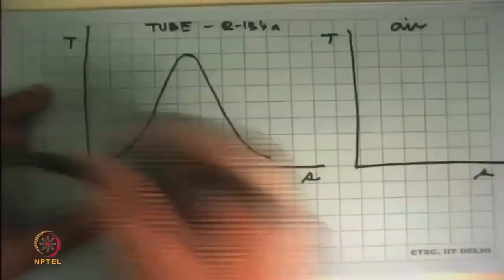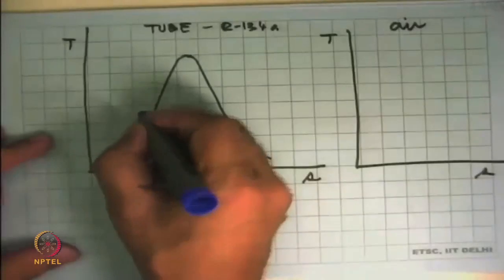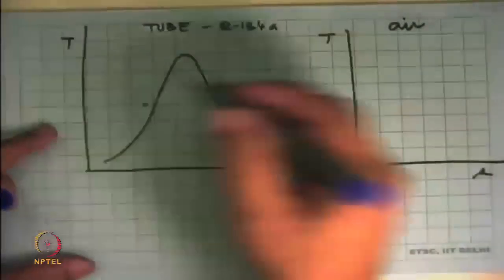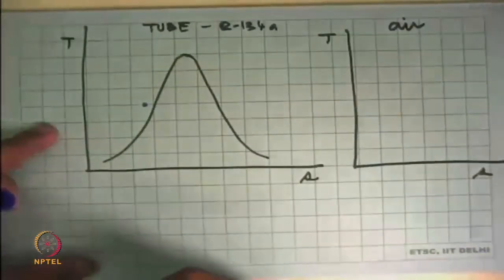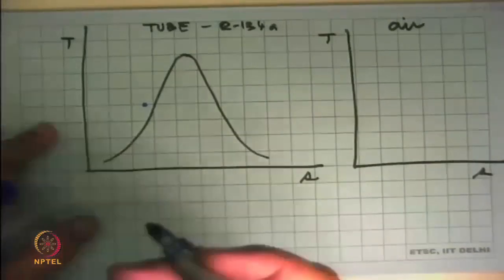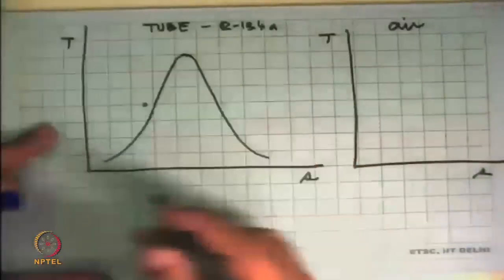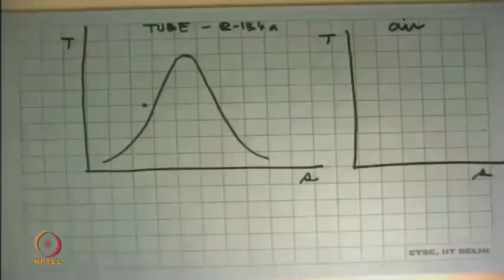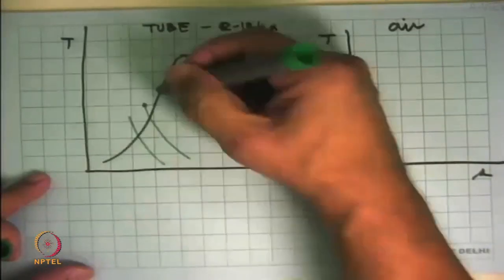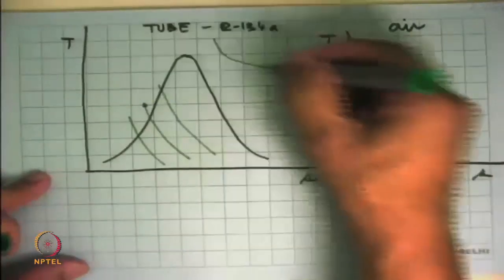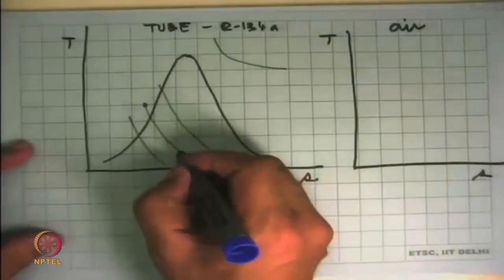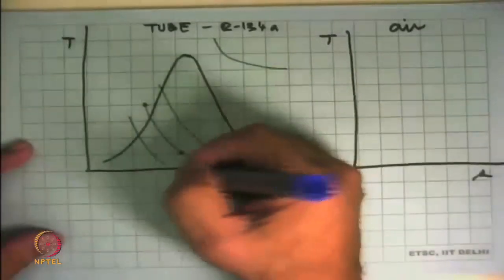So in this case, what is happening is that at the end of the condenser, we got slightly subcooled liquid, and this was throttled. Now, throttling is a highly irreversible process, so we don't know what states happen in between. But at the end, we know that the enthalpy doesn't change, so it will follow a constant enthalpy line. And constant enthalpy lines on a T-s diagram look like this. So the inlet state to the expansion valve was there, and the outlet state was there. In between, we do not know what happened.